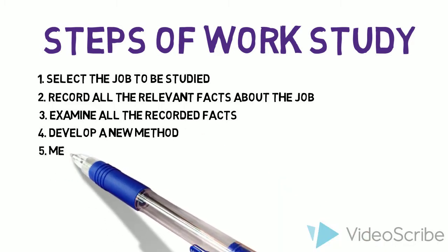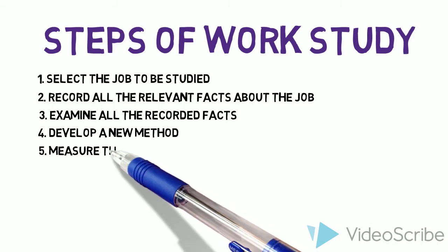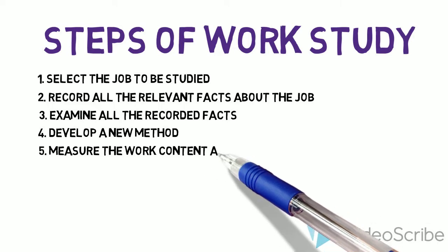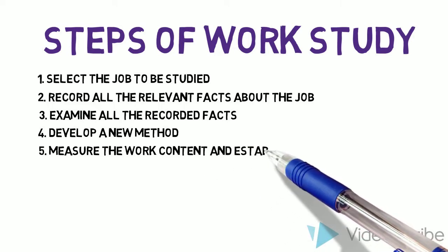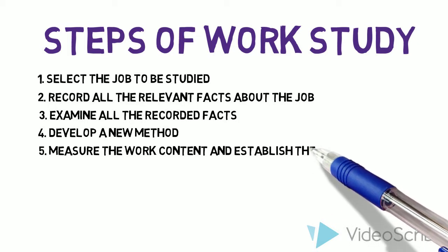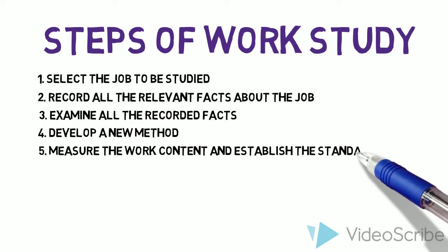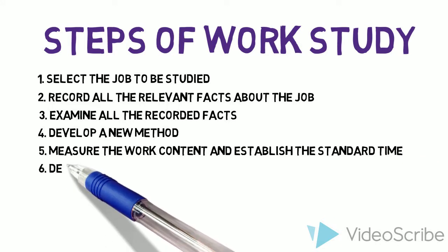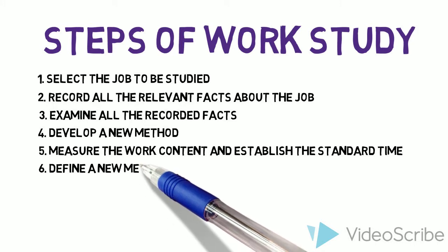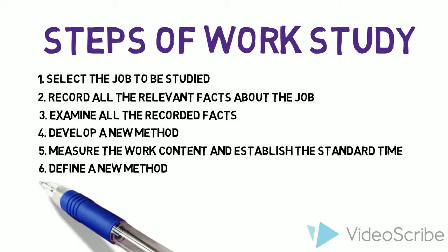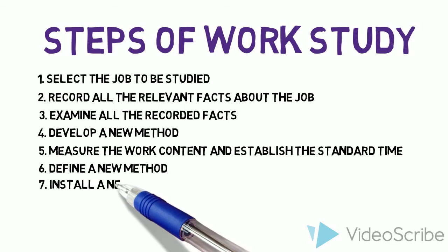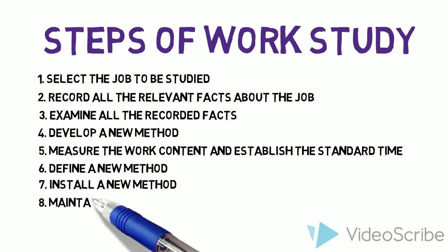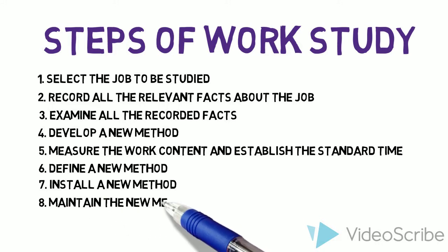Step 5 then allows you to measure the work content and establish the standard time. For now we will just use a stopwatch analysis. We will see how long it takes for each method to be done, and then pick the method that takes up less time. For number 6, we then fully define this method, and then step 7, we install it by implementing it, and step 8, we maintain it by making sure we enforce it and make sure that everyone uses it.